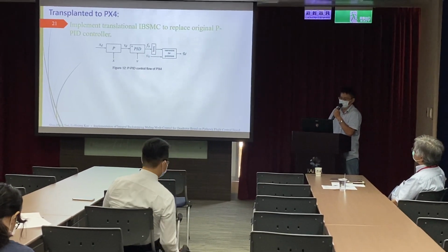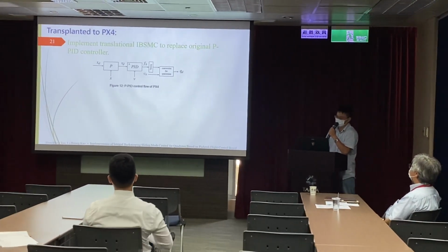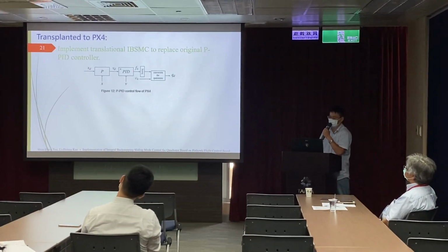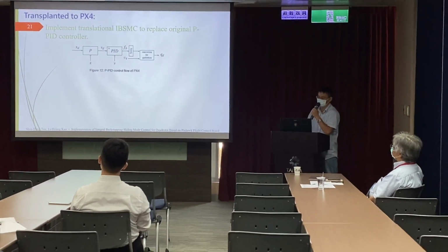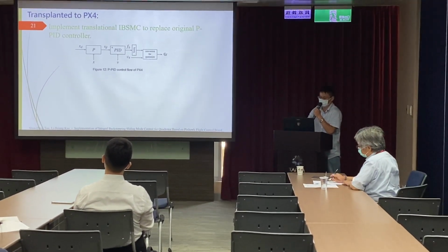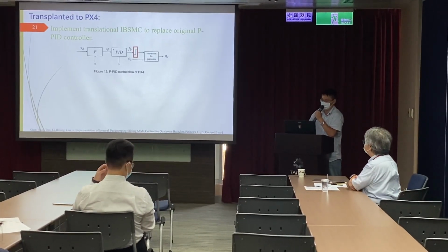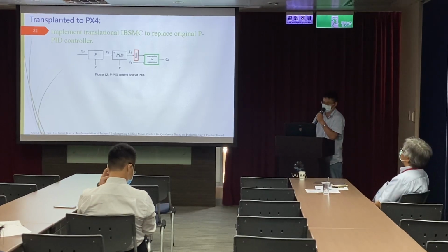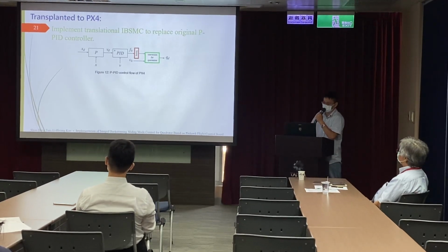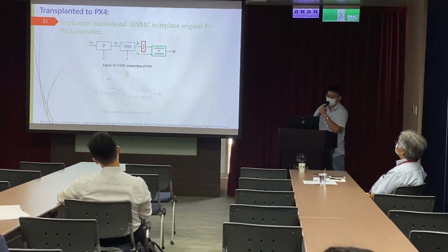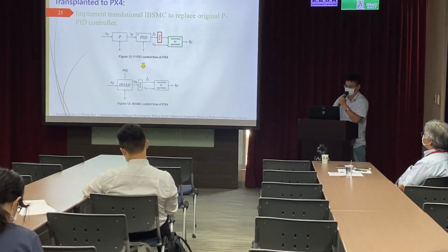The PID is the original control method in Pixhawk for both translational and attitude controllers, and we revised the translational part. To collaborate with the real situations, the controlling output must have a limitation to meet the motor's constraint. And after that, it is merged with the direction angle to convert to quaternion. These two steps are different from the simulation, and our job is to implement the IPSMC to replace the original part of the PID controller.